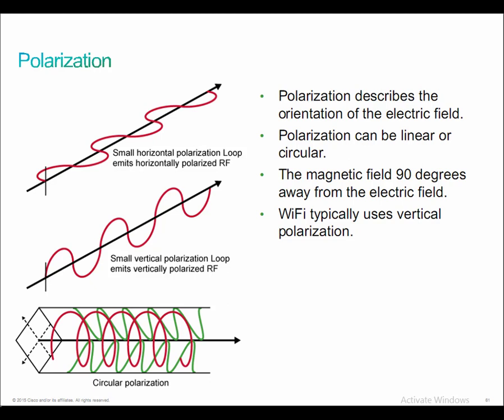The H and the E plane patterns are usually different. So what does that mean? That means that the antenna does not radiate in the same way in all dimensions. And that makes sense, right? You have a patch antenna, it's going to send very little over the elevation plane, but a lot in one direction on the horizontal plane. Or you have an omnidirectional antenna, which sends a signal out in 360 degrees, but very little signal above and below the antenna in the elevation plane, but propagating outwards on the horizontal plane.